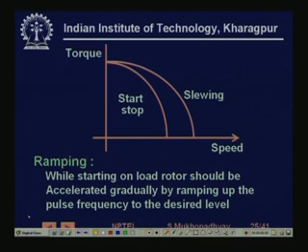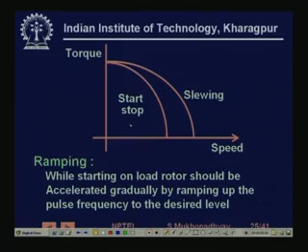So if you see the torque speed characteristic, we will see that when one is trying to start the motor, that is when the motor has no inertia, it is not moving, it is actually at rest, then initially you have to start it. You cannot give very high frequency pulses, because if you increase the pulse frequency too much, before the rotor can move, another phase will be excited. So with respect to that phase, since the rotor has not moved, its torque will not be enough to move the rotor.